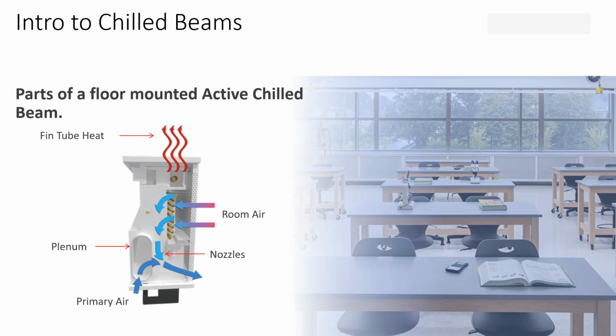And the thermal plumes in the space generated by the heat loads, in this case, it'd be students or a teacher or computers at the desks, that's warming up the air around them, and that warm air in a displacement stratified system wants to rise up naturally. So, contaminants, things from breathing associated with thermal plumes or the heat loads, in the case of an occupant breathing, a lot of those contaminants are effectively pushed up and displaced to that upper zone instead of mixing everything uniformly throughout like a dilution system.